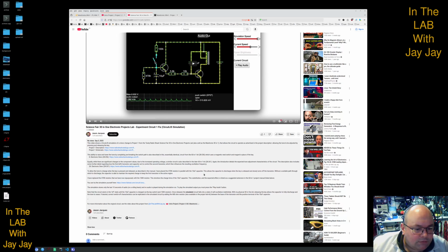I have replaced the 470k resistor that we have now repurposed with the 100k resistor. This shortens the charge time of the 10 µF capacitor. This substitution and the expected effect is listed as a suggested extension in the 60in1 project manual linked above. You can try the simulation yourself here.